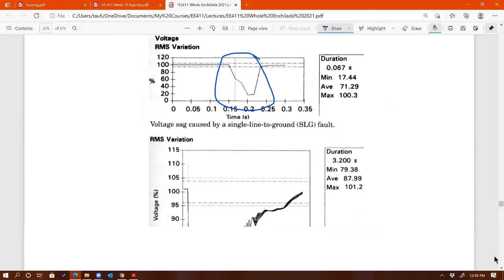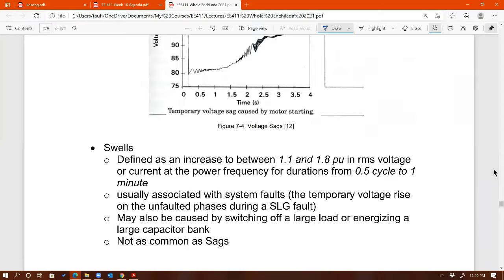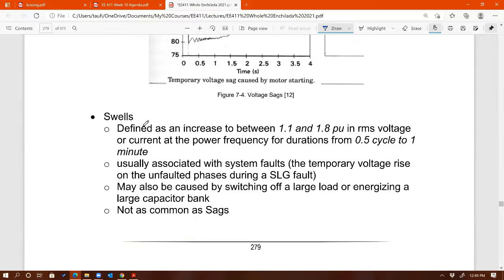So you have slip equations, and in an induction motor, slip could never be 0, because the induction machine is always lagging. The rotor flux is always lagging the air gap flux. Right. Okay. Very good. You still remember.